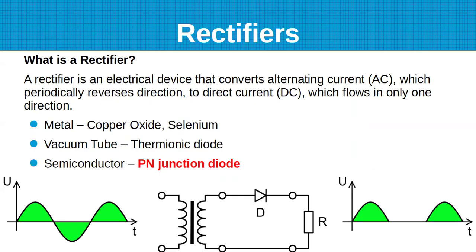That's used in power supplies where we can take the AC voltage from a transformer. Say this was a step down, like we talked about last week, where 120 volts on the primary and 12 volts on the secondary. If we put a diode in the loop prior to the load, we're going to see it conduct on the positive half cycles of that wave. So we'll get these DC pulses. And if we run that through a filter capacitor, we'll get kind of a constant DC value.